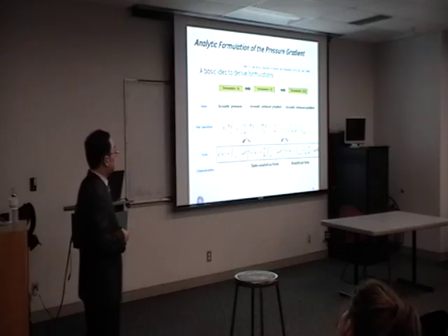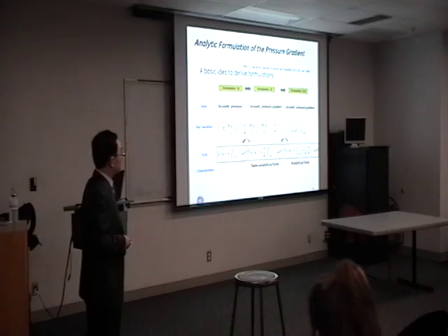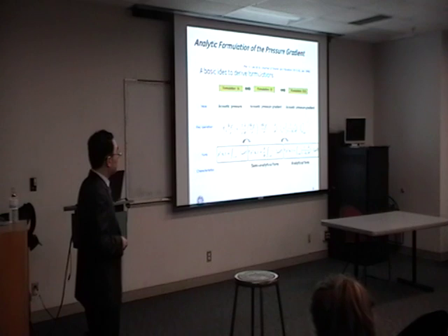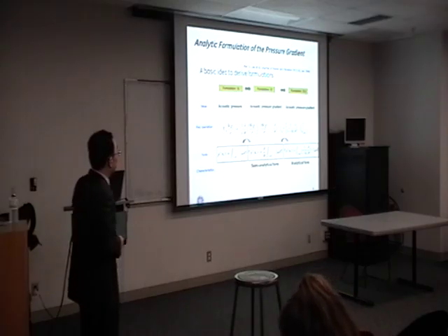The benefit of this conversion is that we can take the source time derivative inside the integral and then take it of each component here, which is also calculated at the source time. So this gives a full analytic solution of the pressure gradient. I named this one formulation G1A.